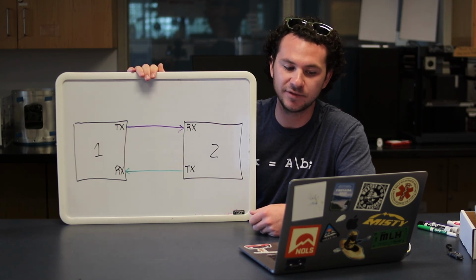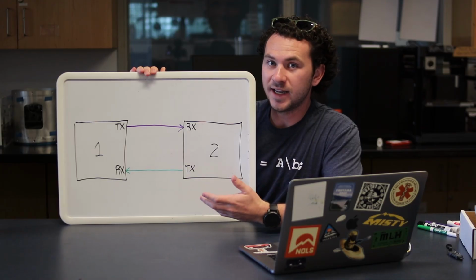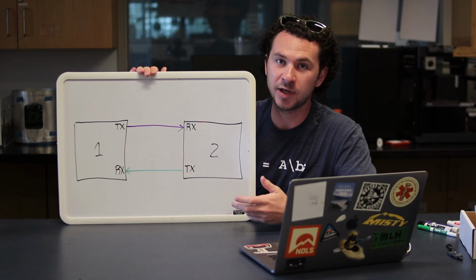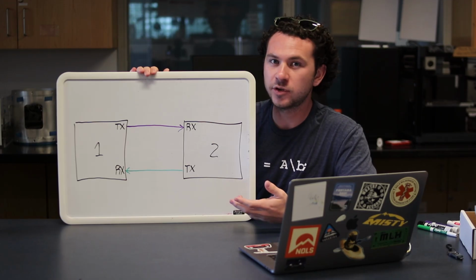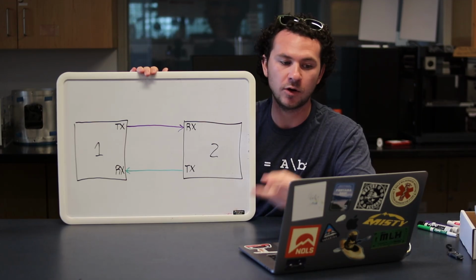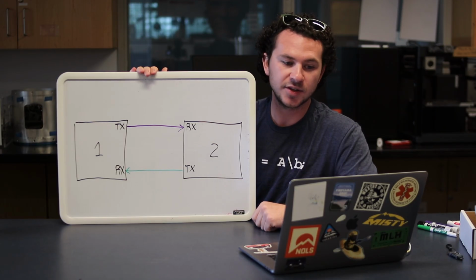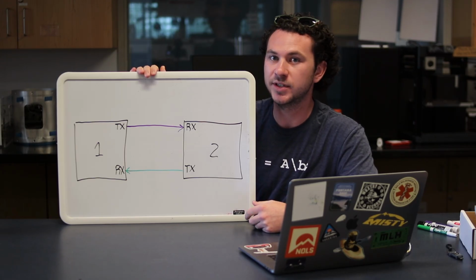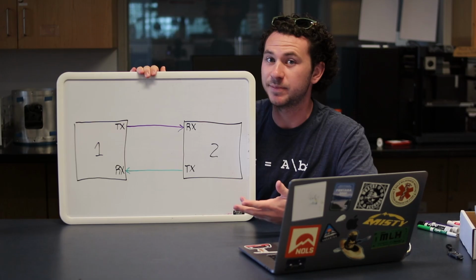This makes UART communication slower than the previous two communication protocols we've looked at, but it does simplify communication from a hardware perspective. This is all the wiring that UART communication requires. Just two wires, and a common ground as always. Unfortunately, UART is best for connecting only two devices, so this protocol isn't great for building the larger networks of devices we can put together with I2C or SPI.